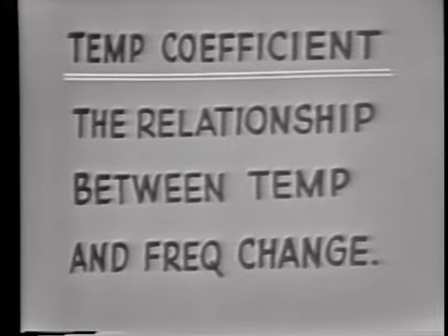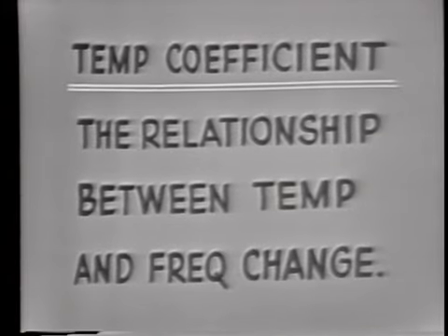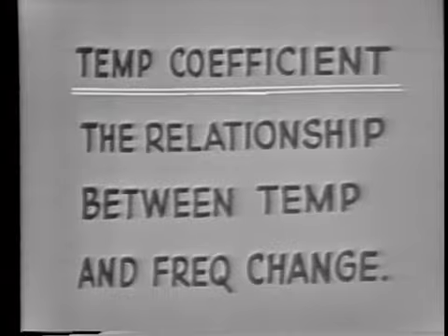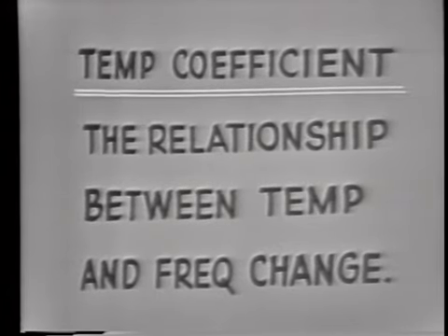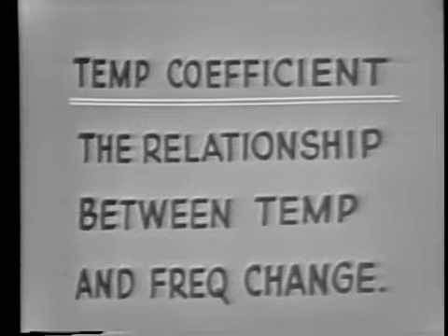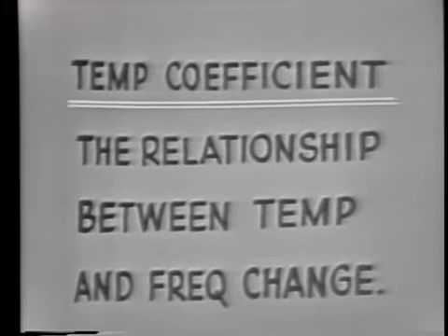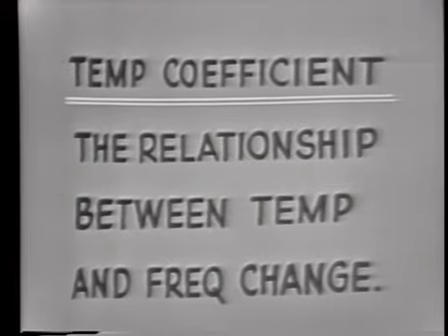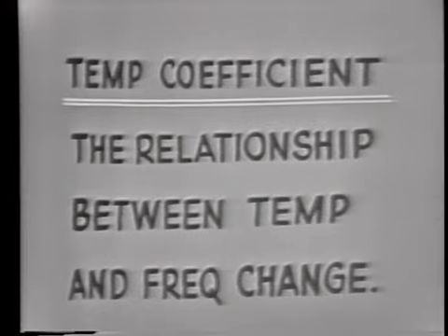Now, another characteristic which will be different for the various crystal cuts is the temperature coefficient of the crystal. The temperature coefficient. Now, this is a new term, so let's define it. Temperature coefficient is the relationship between temperature and frequency change. Then at this time, complete item 6 in your TVI guide. Temperature coefficient is actually the effect that a change in temperature will have on the frequency of the crystal.